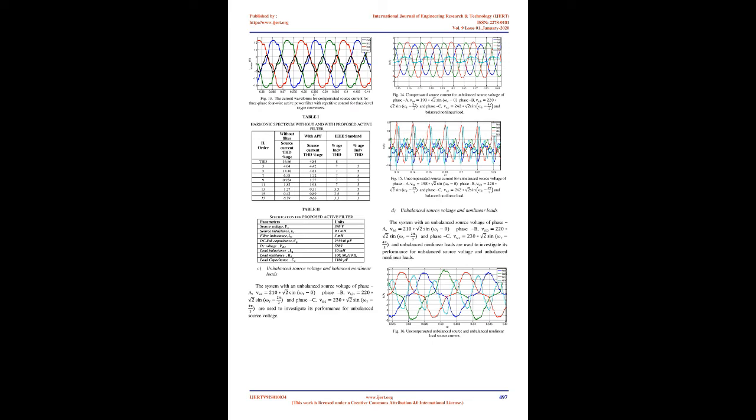For simulation results and discussion. Various MATLAB/Simulink toolboxes are used to simulate and design the proposed system of 3-phase 4-wire with 3-level T-type inverter. The 6 outer IGBTs form the 3-phase converter and the other 6 IGBTs form the inner circuits. The simulation incorporates various balanced and unbalanced loads such as 3-phase as well as single-phase nonlinear loads. The investigation also includes unbalanced source voltage and unbalanced 3-phase 4-wire nonlinear load.